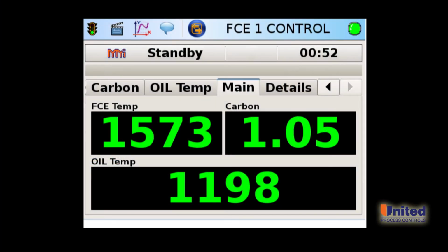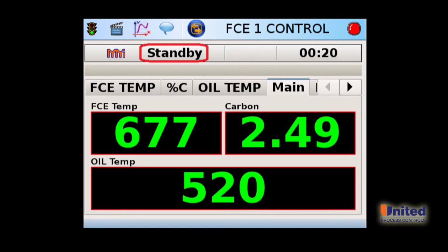Go to Control. Control is running right now in standby mode. That means that it's just maintaining the set points that are configured in each loop at the moment. There is also a standby logging mode, which allows you to record the behavior of the furnace or anything that's been changed in a loop without actually starting a recipe. This is real handy for things like tuning, troubleshooting, trying to determine what may be going on in the furnace without actually changing any recipes or walking through a recipe.